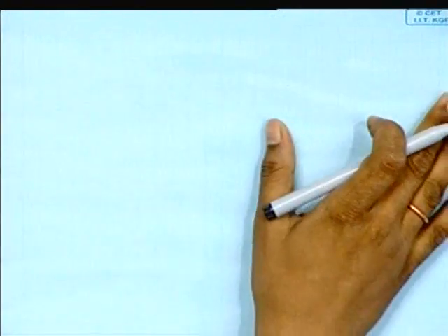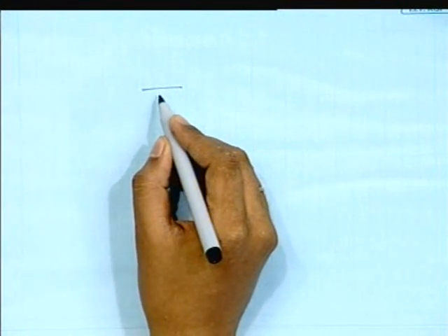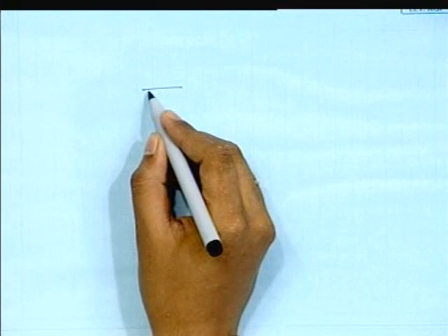Whenever we analyze the circuit in the small signal model, we take that node as a ground, which is called the AC ground. Okay, now we want to draw the small signal circuit of that resistive load CS stage.